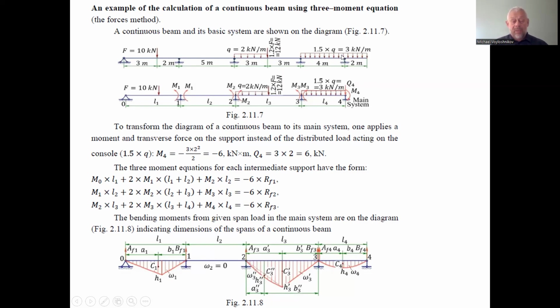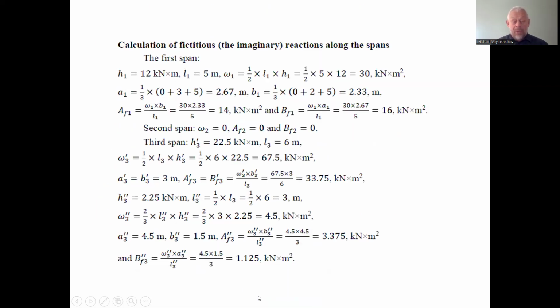To the right, we have evenly distributed load, and we have the parabolic shape of a curvilinear bending moment diagram. So we only need to find the magnitudes of the vertices of the triangle diagram or this parabolic diagram, with one triangle diagram and a parabolic segment.